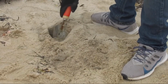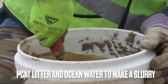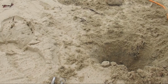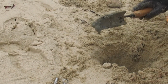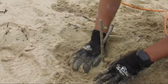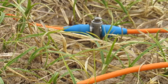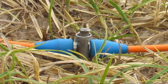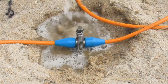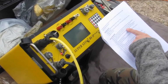When digging holes to place electrodes in, depending on your site, you may need to add salt water and cat litter. Cat litter has a high clay content that holds moisture and enforces connection of electrodes. Mix cat litter with salt water in a bucket for a paste-like formula to add in the holes for electrodes. Be sure to make the holes narrow and deep for better contact with the earth. We then hammer the electrodes into the ground so that only about an inch sticks out, just enough to see the connector. If contact resistivity issues persist later on, it can typically be solved through the addition of more cat litter and salt water. Again, use your SuperSting manual for specific instructions on how to run the test.